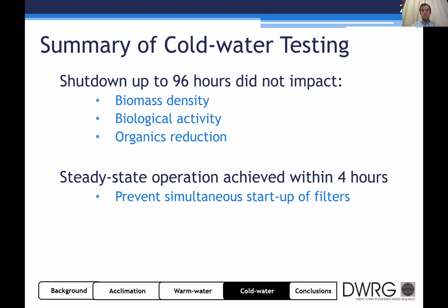However, it is important to note that we achieve steady state within 4 hours. And in a pilot study like this, it's important to contextualize these results and say, we can avoid this at full scale if we prevent simultaneous startup of filters. So if we stagger the startup of filters by more than 4 hours, there's only ever one filter that's going through this potentially impacted water quality.